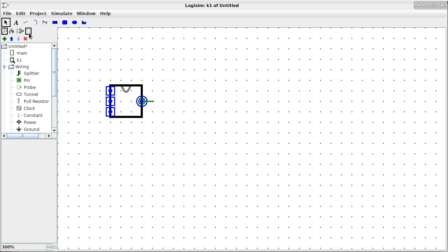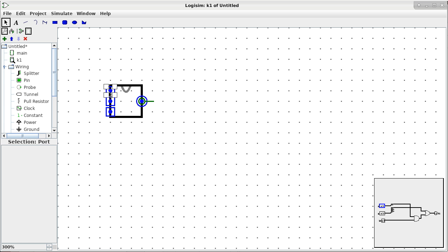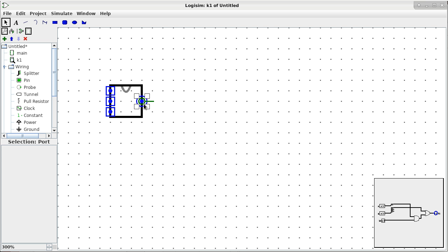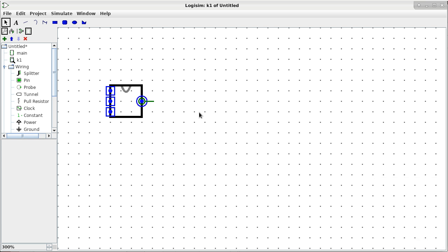Okay? But if you're not 100% sure, one thing you can do is to click on the pin and see which one it connects to in the design. This is a pretty handy feature, and you can double check and make sure that we have P, G, and K0 like that. And also K1 is the output. If you click on K1, which is a little bit harder because the orientation pin is also here, you can still click it. Does everybody see what I'm talking about? You can map what we call the port of the appearance to the pins of the actual design.